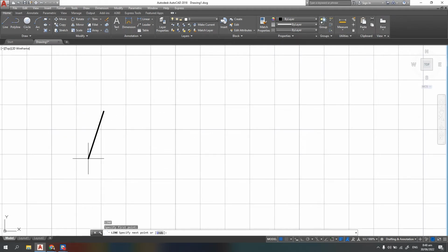So how can we draw a square if we don't know the exact coordinate for that? We don't have an idea of the next one. To answer that question, all you need to do is draw using the relative coordinate entry, the second method. Okay?